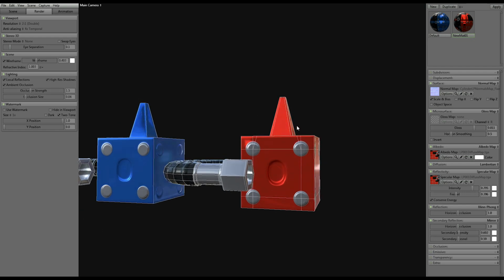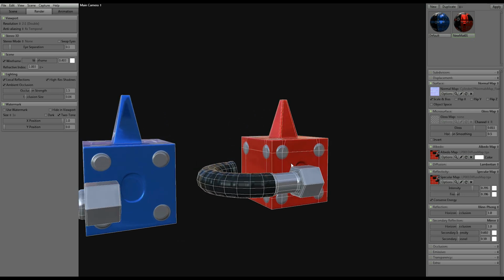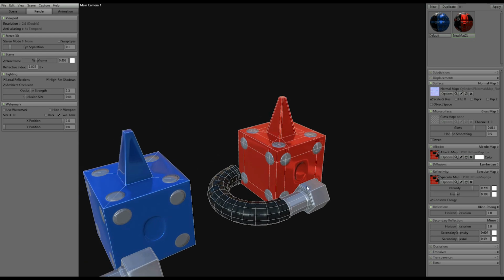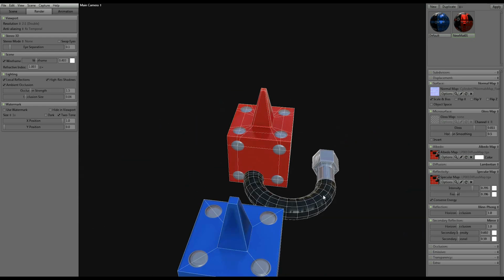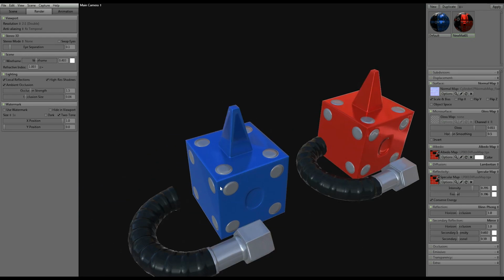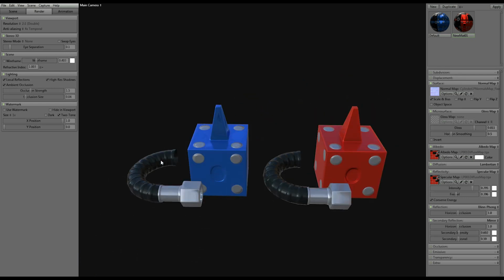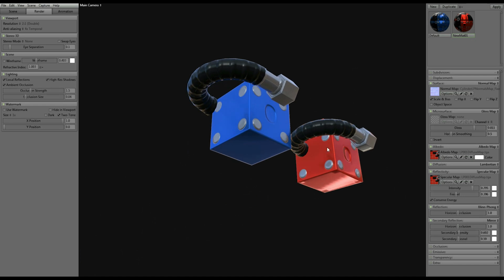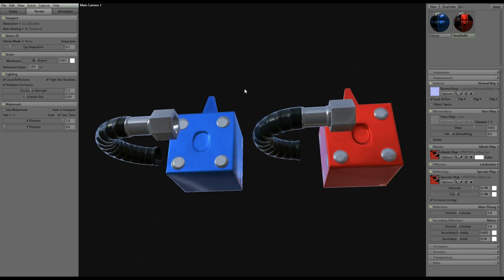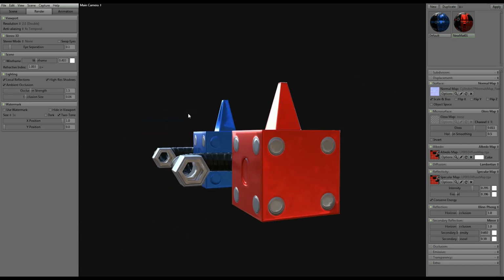And then, not necessarily angle related, inserting vertices in the middle of the high poly floating geometry basically gives you a normal coming straight out of that mesh in that area, and that can help tremendously for stuff like this. Let me turn the wireframe off. Over to the tube, something like this, we didn't run into any issues. There's really no baking errors here on either of the sides, so that was fine there. But once again, we don't have a lot of steep, hard angles like this here.